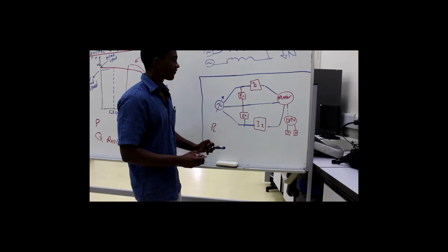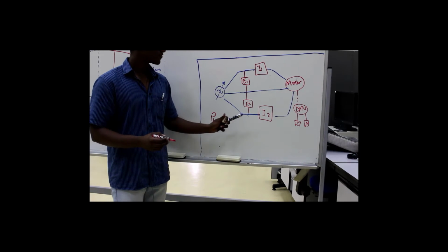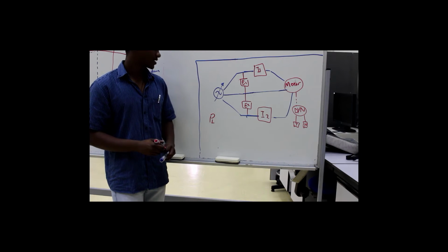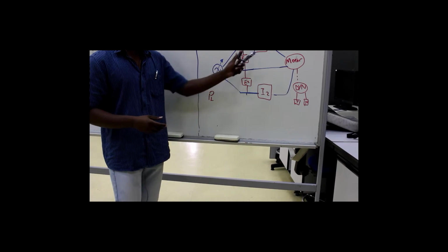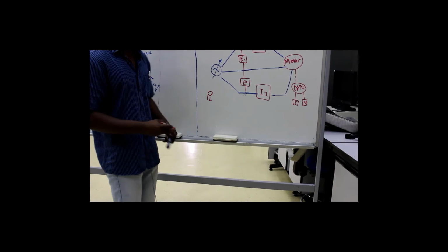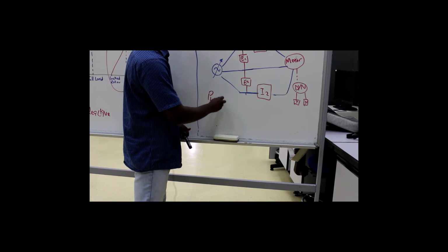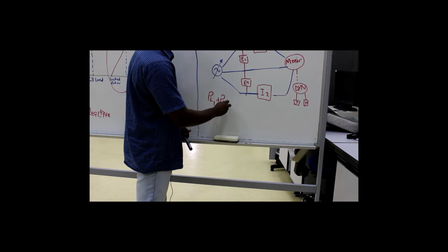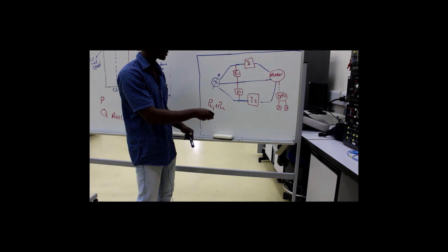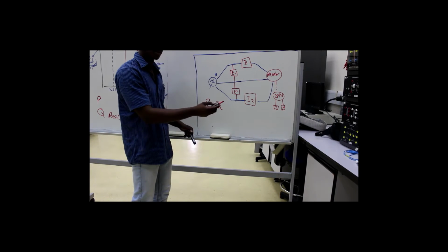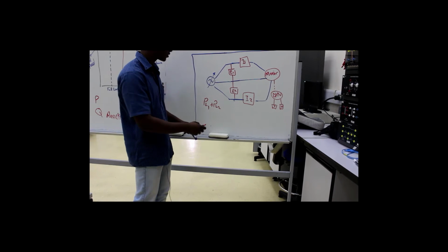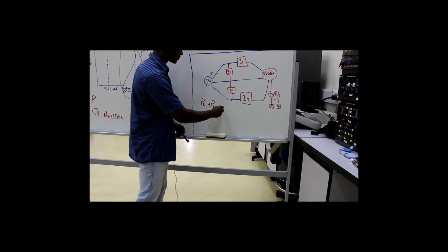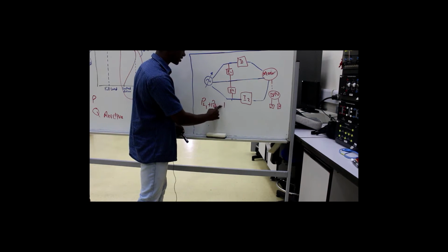Now from the Circuits 2 course, we knew that to get the total power from the line measurements, we have to add PL1 plus PL2. We have to take two measurements of the line voltages and currents and get the power in the metering application, as I will show you, and sum them up to get the total power.